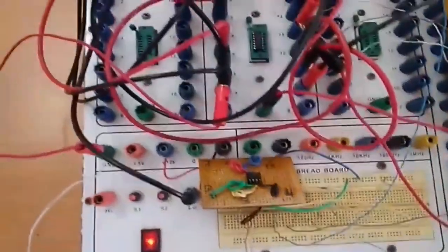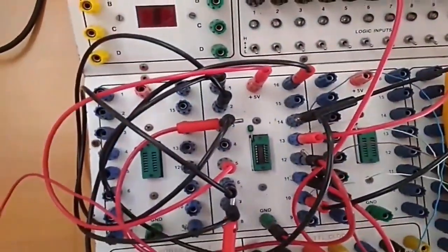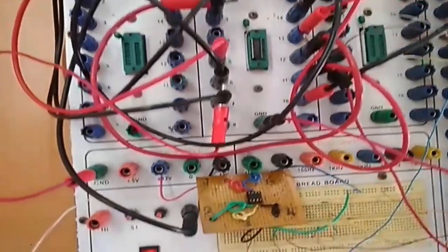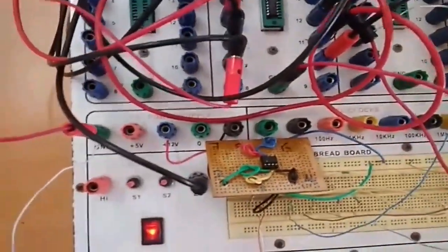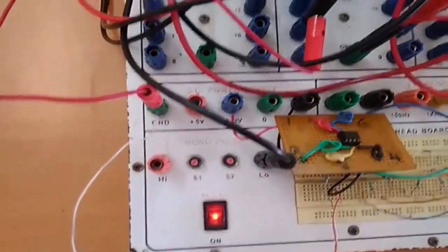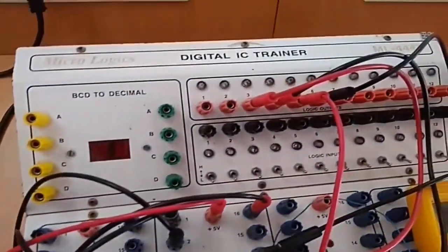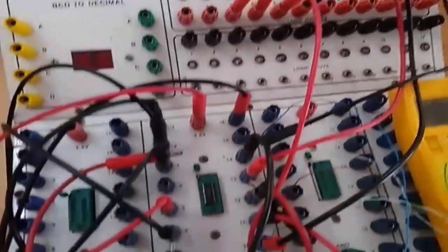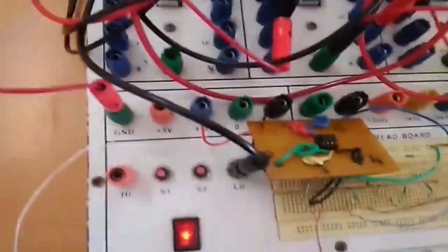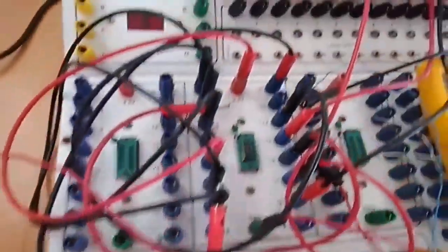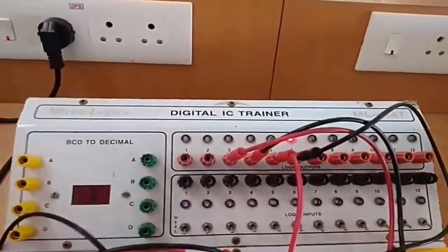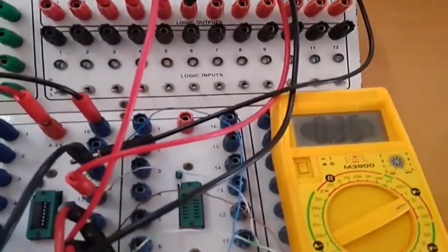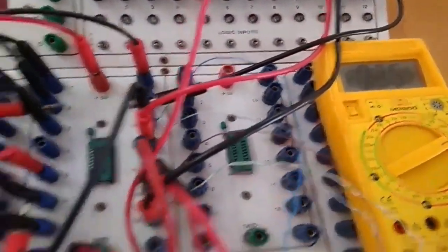Now going to the circuit diagram, I have used IC 7493, and the output of that is given to the DAC. When I apply a clock pulse through these switches, the counter output will change. This is the counter output, and that is given as input for my DAC, and I have to observe the output voltage in the multimeter. When I apply the first clock pulse, my counter changes to the state 0001. At that time the voltage is around 0.35. I'm expecting 0.21, so I'm getting a bit extra.